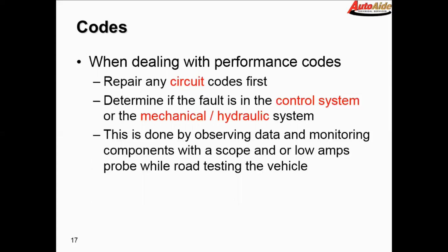They could be leaking hydraulically, or it's not impossible to have a check ball or a pintle stuck or something like that. This sounds easy in theory. It's not quite as easy as it sounds, but we'll walk you through some of this stuff.